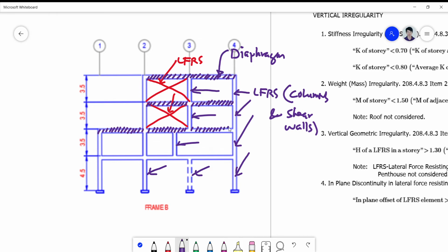Sometimes a portion of your lateral brace can be helping, no, the action of the diaphragm to transfer the loads from one column to the other, but basically the main purpose of a cross bracing is to add to the strength of your LFRS system. So mainly the diaphragm is made by slabs and beams. Okay.